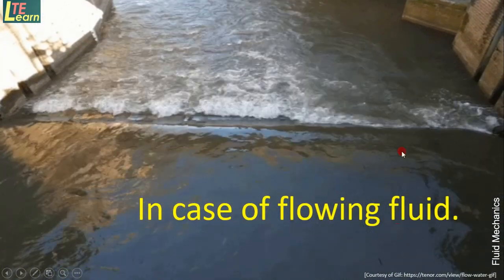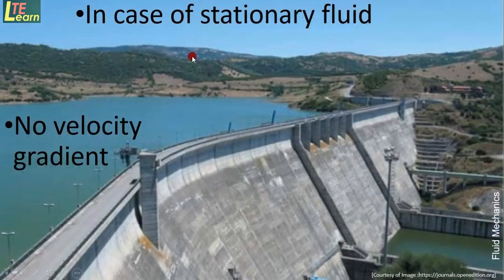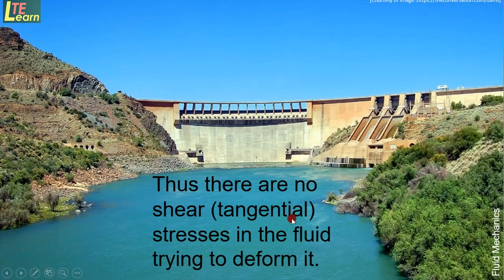In case of flowing fluid, here we find this fluid is flowing in the form of different layers. So here a velocity gradient exists, that is called du upon dy. Here one layer is trying to drag another layer, so that's why shear stress is developing between the layers. But in case of stationary fluid, as there is no velocity gradient present, there are no shear or tangential stresses in the fluid.